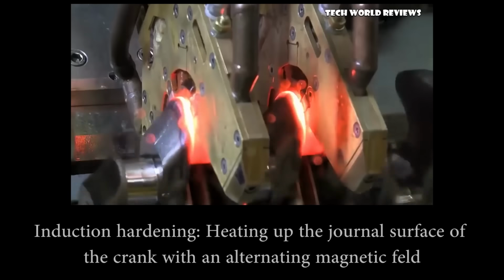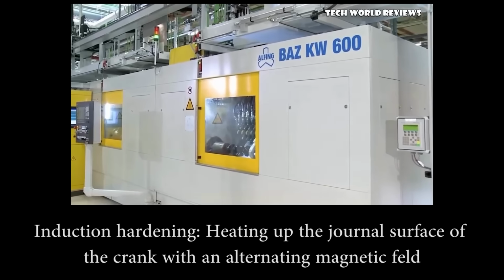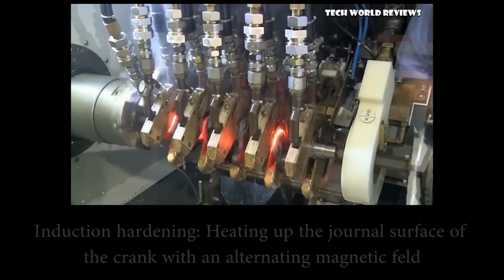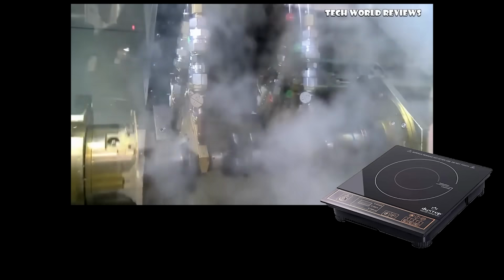Most OEM crankshafts undergo something known as induction hardening. This is a no-contact process that uses an alternating magnetic field to rapidly heat up the journal surface of the crankshaft, thereby hardening it. It's sort of similar to how an induction stovetop works. Well, sort of. But it's great because it's really well suited to mass production. It's inexpensive and it's fast.